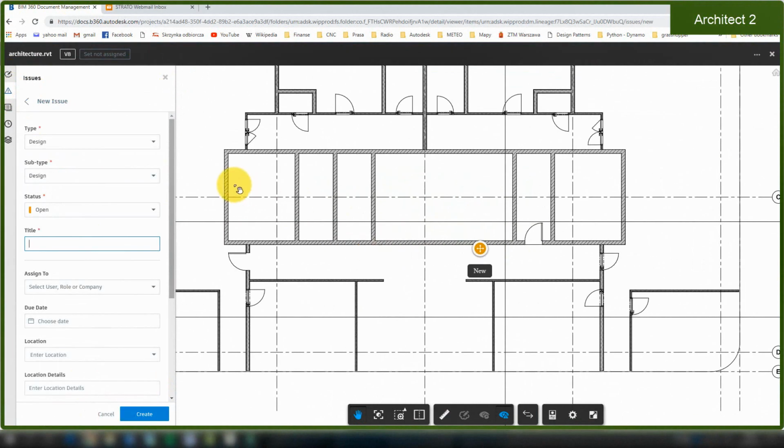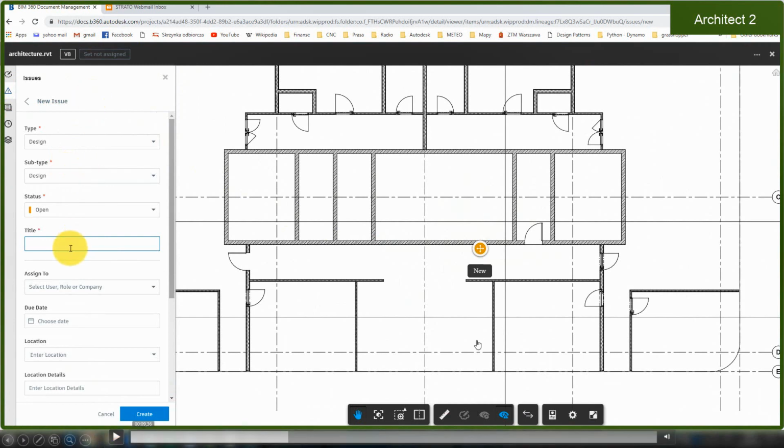changes have been done. And now I'm going to stop for a moment, because what happens here is that Architect 2 is working together with Architect 1, and Architect 1 has, of course, some worksets, so some groups of elements that belong to Architect 1. Belong means that Architect 2 cannot, of course, because they have to work together, but they must not disturb each other, right? So Architect 2 now is going to ask Architect 1 to release some elements.